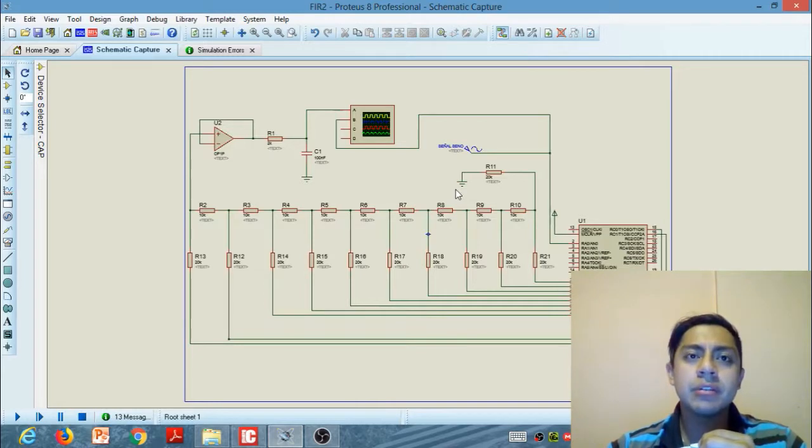The operating methodology assumes the response to the impulse of the system, a way of describing a system. Theoretically, it never goes to zero, which is clearer than in reality. The signal eventually falls below the noise floor, so in practice it is not infinite. Due to the use of feedback, IIR filters can be unstable.